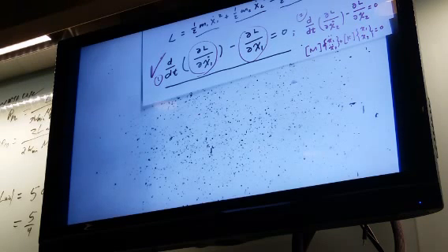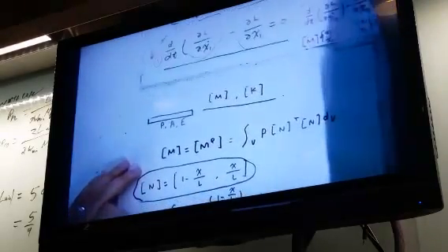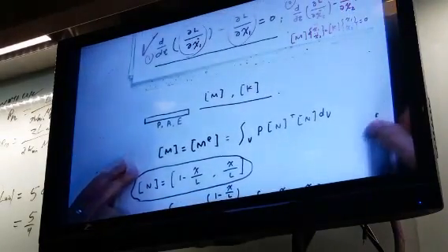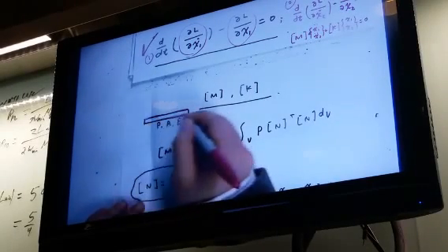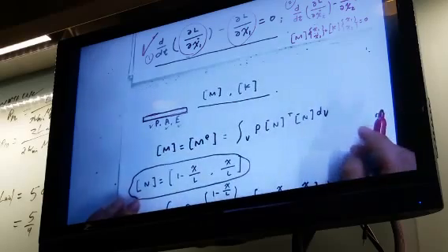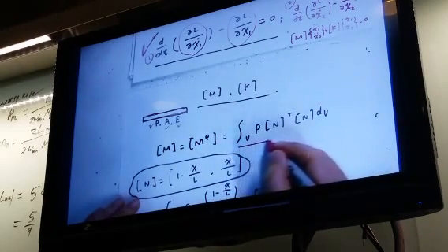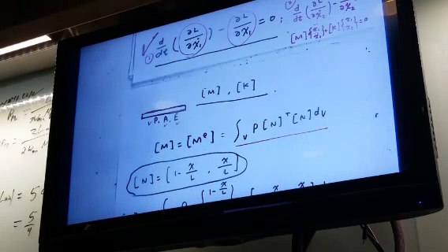But for a continuous system, we did some derivation. For bar or beam, how are we going to form the mass matrix and the stiffness matrix? This is one elastic bar, with density, cross-section area, and Young's modulus. And this is the mass matrix we should have for this elastic bar.